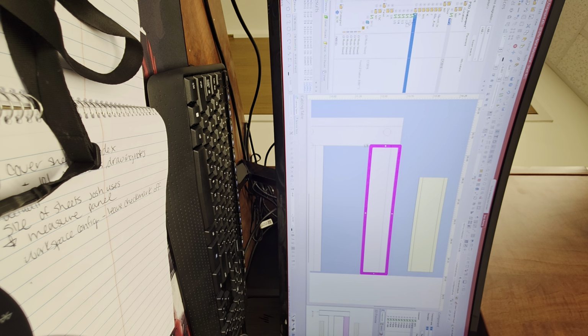Do the same thing for the item that says MP2 up above. Let me select that one. What was that one? Is that the plate? Yes. That's the mounting plate. So that one goes into the MP4. Actually, expanded MP. Is that the one actually placed? That's the one that's not placed currently. Expanded. That's the one that can be deleted. Right. When it shows yellow as unplaced, then we can select MP2 and just delete this as a device.